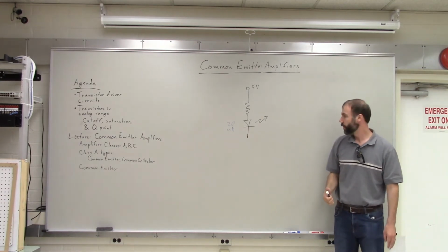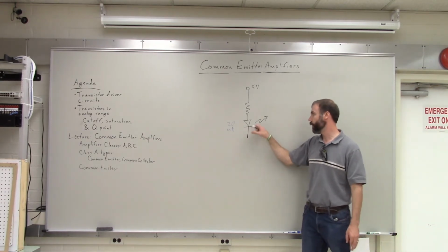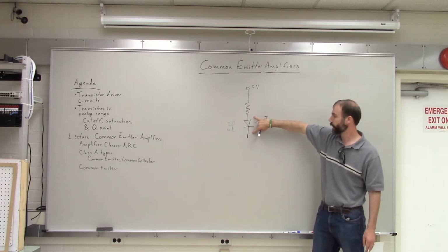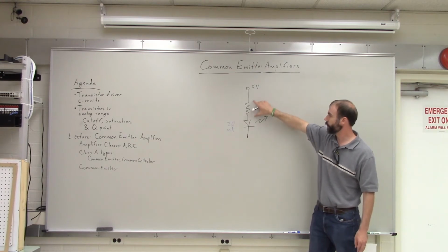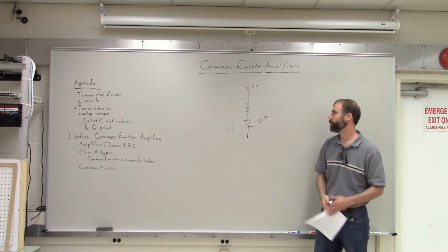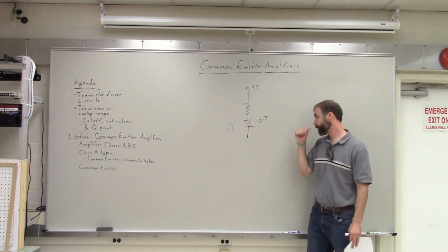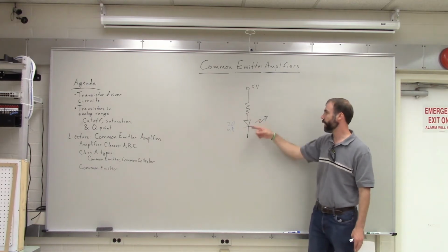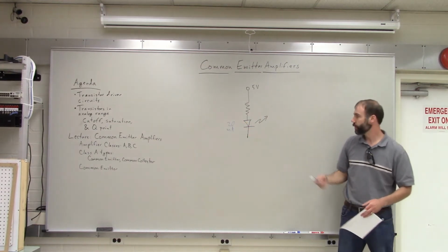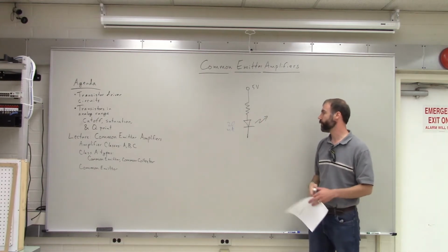So we could do the calculation. We know that there's 1.5 volts across the LED when it's running. And we have a 5-volt there, so we know that there's 3.5 volts across the resistor. So then you could figure out how much resistance you need to get 20 milliamps with 3.5 volts. So we pick that resistor first.